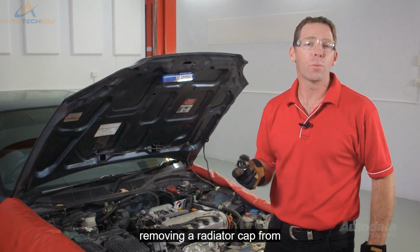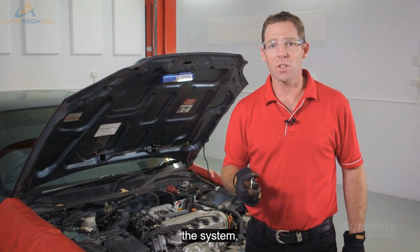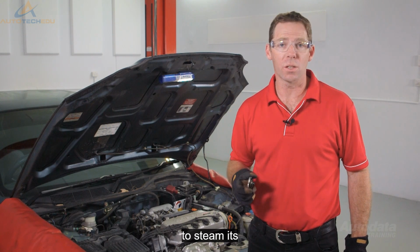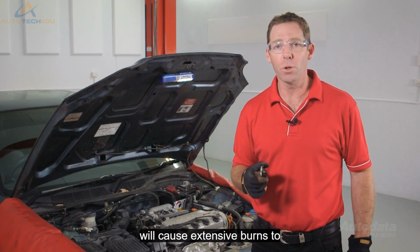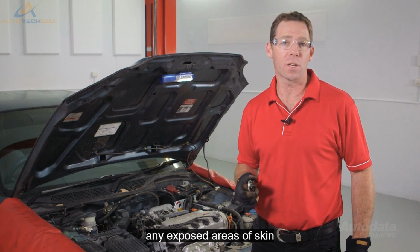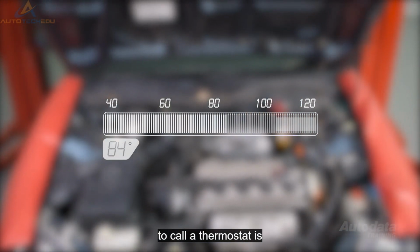Removing a radiator cap from a hot engine is extremely dangerous. As the coolant exits the system, it loses pressure and converts to steam. Its temperature remains high and will cause extensive burns to any exposed areas of skin. Ideally, a system should be left to cool.